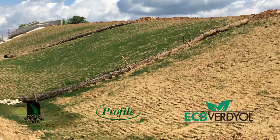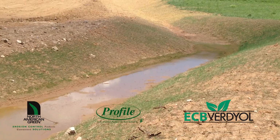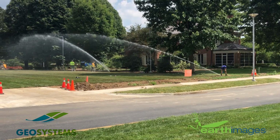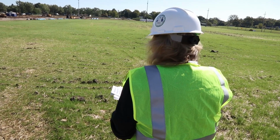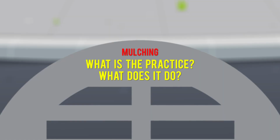If vegetation fails to grow, consider soil testing to determine soil pH or nutrient deficiency problems. Other seed or seed mixtures may need to be selected. If using sod, keep moist until fully rooted. How to inspect. Inspectors should check for evidence of erosion or movement of mulch as well as adequate cover, 80% density. Mulching, including hydro-mulch and straw.